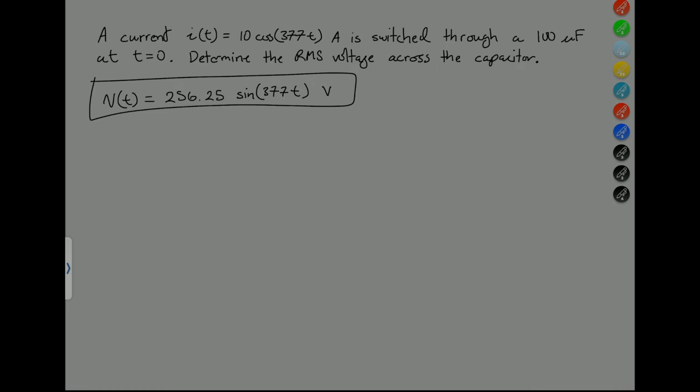Welcome back. This is Ink, and in today's video, we want to calculate the average power and the instantaneous power in the capacitor. So our average power is equal to 1 over the period multiplied by the integration of our instantaneous power over 1 period, and that should be equal to 0. And we'll prove that by using our LTspice simulation.